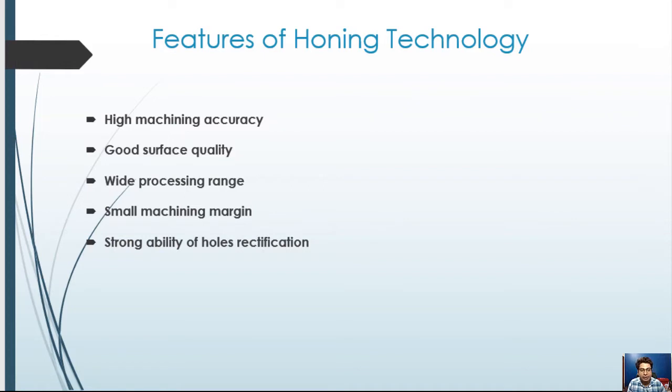The grinding accuracy is worse for small hole precision. Generally, honing can only improve the shape accuracy of the workpiece. If we want to improve the position accuracy of the workpiece, we should take some necessary alternate measures.